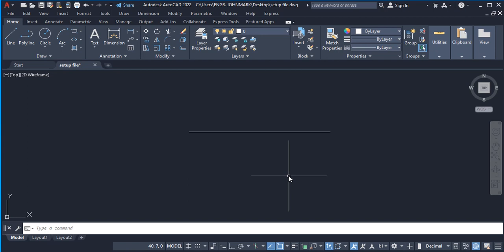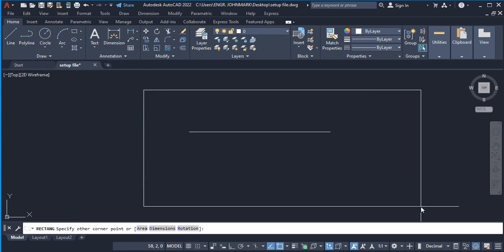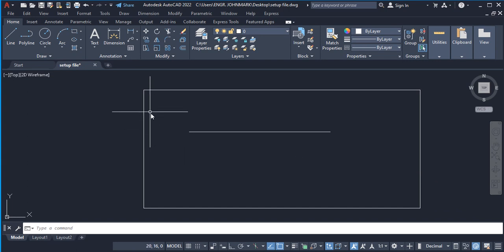the drawing limits. Actually, what the limits talks about is that if, for example, I pick a square here and I draw here, the limit within which you're going to be making your drawing is within this box. That's what the drawing limit is all about. So I'm going to do that setup in order to create a boundary, because this workspace seen here is more or less like infinity. So you are creating a limit within which you'll be making your drawing so that whatever you draw, you can actually see it. And then we are going to be setting that up.